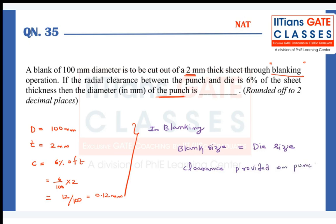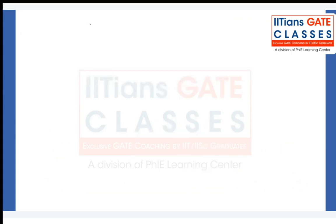All right. Now here punch size is what we need to find, punch size only, right? Punch size is equal to die size minus 2c, or blank size minus 2c. Both are same. Blank size is equal to die size, isn't it? Minus 2c, right? Now let us move to the blank size.